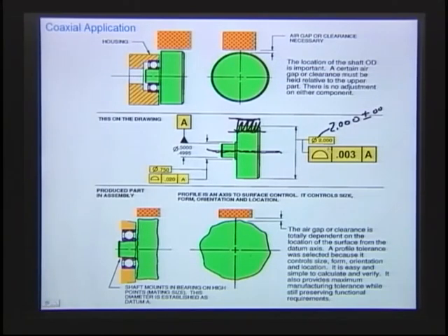Would runout work? Yeah, I suppose you could put a runout on there, but you've got the same problem with runout. Remember, you're going to have to put some size on here, and you're going to have to say that's 2 inches plus or minus what? You know, how big this thing has to be and how much you can be off the center. Look, just don't let it get too close. Don't let it get too far.